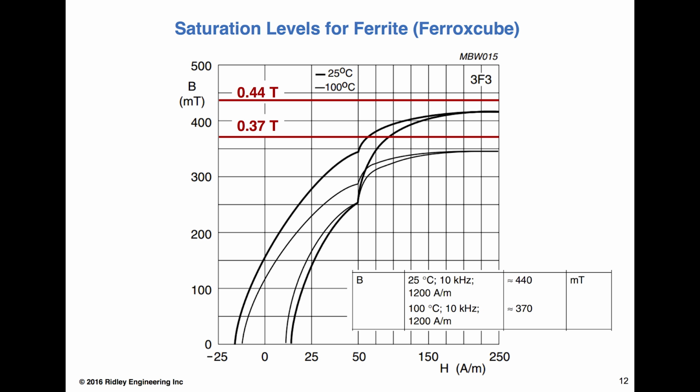Hey, where does the aerospace 0.25 Tesla Bmax requirement come from? Well, from a practical point of view, 0.3 is about what you can do, and then they've just put a 20% margin on that and say, okay, this is the absolute. We shall never, ever have a design that exceeds this. So they're just being conservative, but it's a good conservative, certainly for a mission-critical situation.